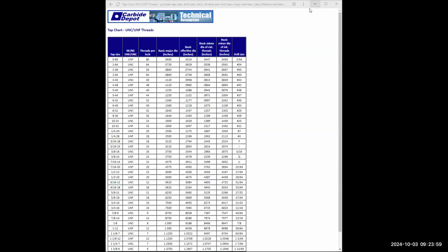We're going to get this hole here. I'm going to bring it down this way. I'm going to put my dimensions in a different place this time. All right, watch what I'm going to do. I've only got like 16 minutes left. So I'm going to type in leader, enter. Type in near, enter. When you type in near, it's going to snap to the nearest point of that cursor. Click.